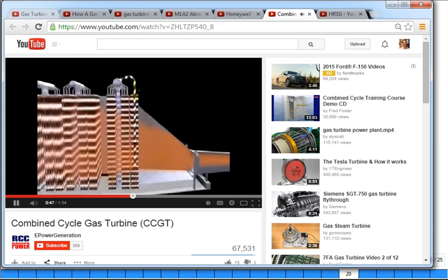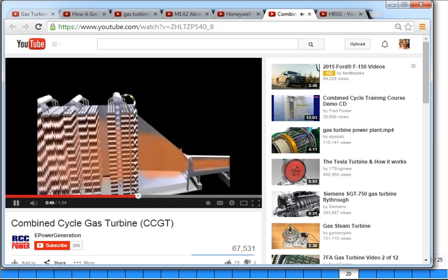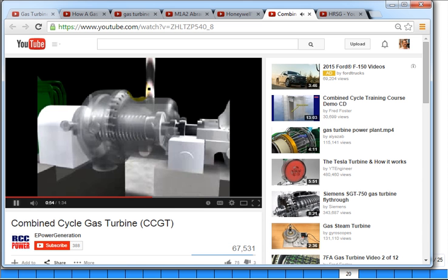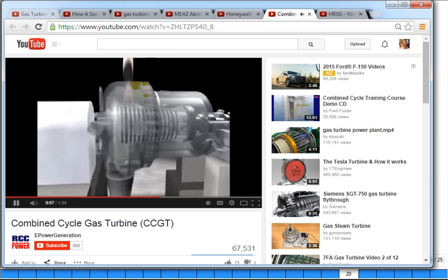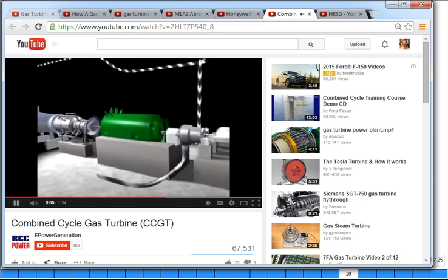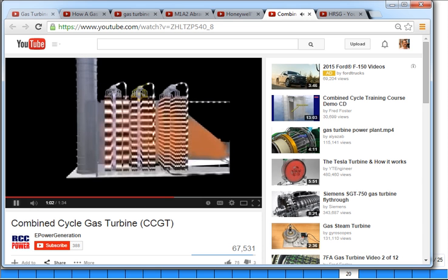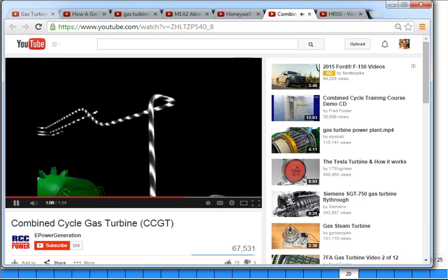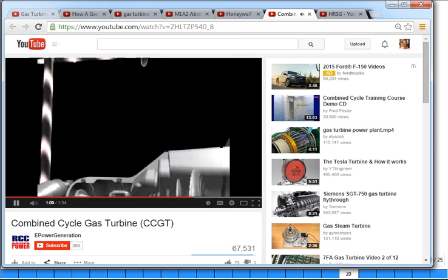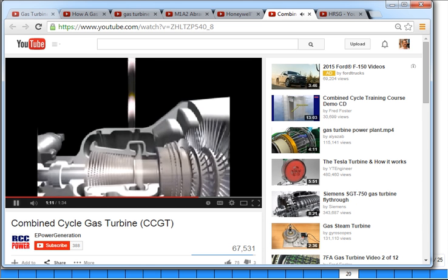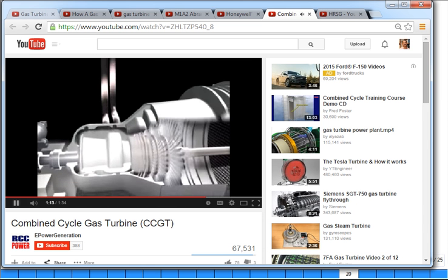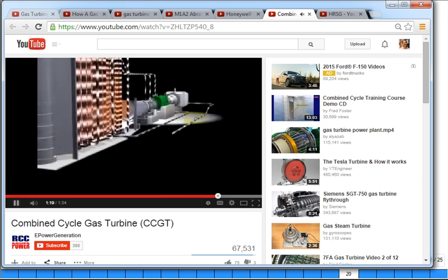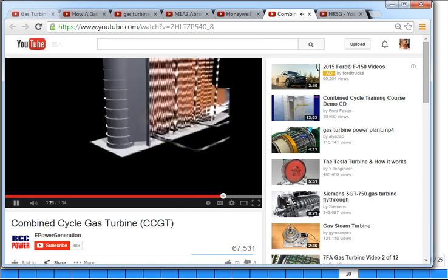That is now water. They're showing steam. Okay? It's being piped out and brought back to a steam turbine. That'd be a high pressure steam turbine. Then go back for reheat. Pipe it back, low pressure and intermediate pressure steam turbine. Finally take the steam to a condenser and a pump and bring it back. So it's now ready to go.